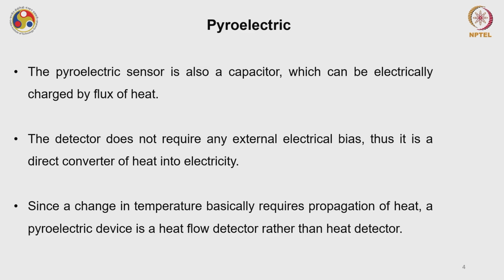The detector does not require any external electric bias. Therefore, it is a direct converter of heat into electricity. Since a change in temperature requires a propagation of heat, a pyroelectric device is a heat flow detector and not a heat detector.